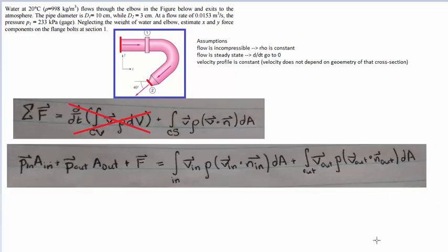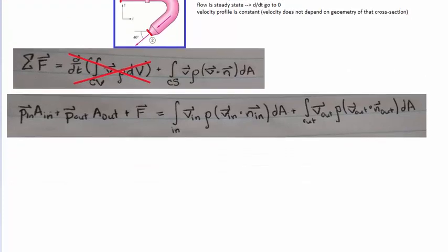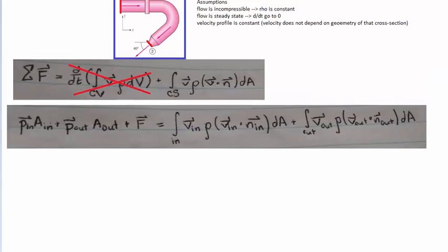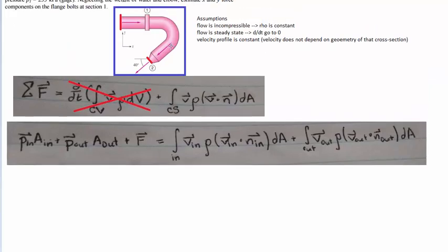So typically there's two ways of solving these sorts of multi-dimensional linear momentum equations. One of them is you go through the system and you basically break each force that you see into components along each dimension. So over here you break this flow into an x-ward direction and a y-ward direction. Same thing for the reaction force, and same thing at the inlet. I would actually recommend just writing all the vector equations and working with the vectors instead, and worrying about decomposing that into two different equations later on.